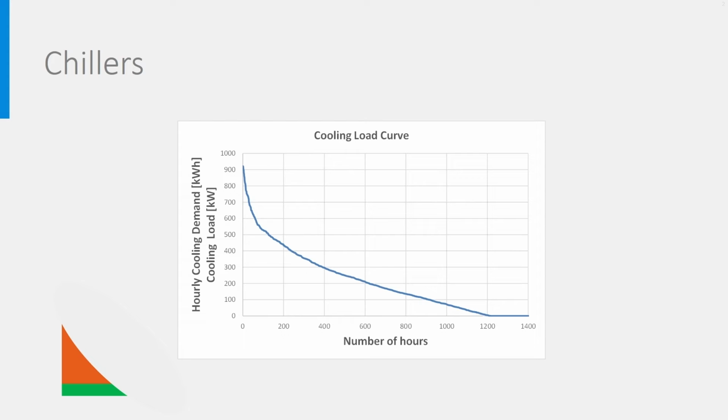For chillers, the problem is different, as there is no alternative technology to cover the peak demand. You remember that to generate cold, only cooling machines can be used, or low-temperature passive technologies like evaporative cooling and natural sources of cold like ground or surface water and aquifer thermal storage. But these renewable technologies do not work at high loads because their temperature is relatively high.